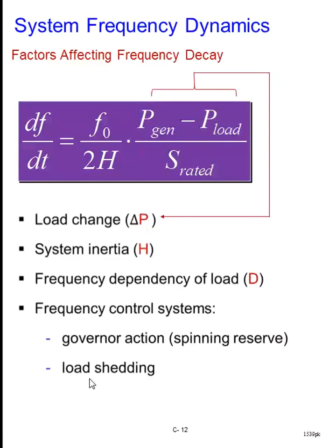Maybe in some of the slides I will show you how this approach is applied. That means how much change in the frequency, what should be the percentage change in the load, that is, the load cutout. So this load shedding we apply whenever we feel that the generation cannot meet the increased demand. In general, these are the two principles for frequency control or frequency regulation that we apply in the network.